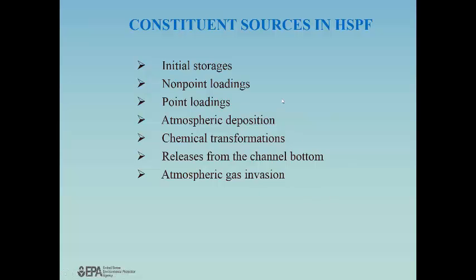Constituent sources in HSPF include initial storages for state variables, non-point loadings that the model simulates, point loadings that need to be defined, quantified, and put into the model, any contributions from the atmosphere, especially in terms of nutrients, chemical transformations, releases from the channel bottom, and for the air-water interface, the transfer across that interface for DO and CO2.